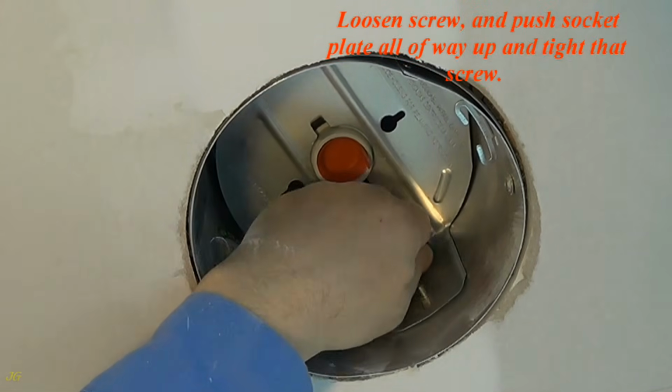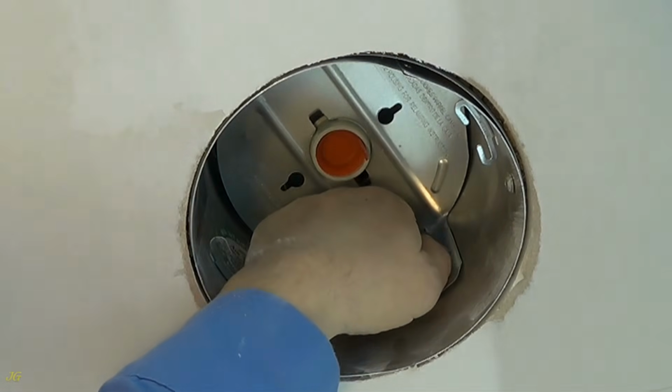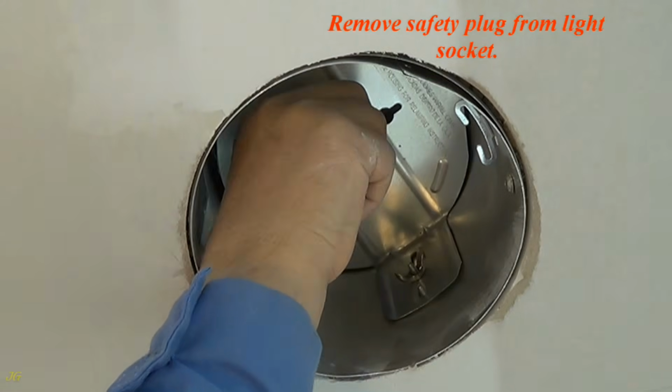Loosen the screw, push the socket plate all the way up, and tighten that screw. Remove the safety plug from the light socket.